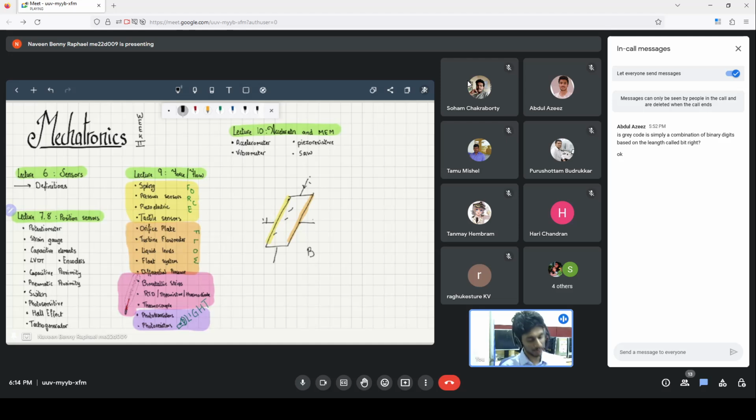If not, let's continue to force, flow, temperature, and light sensors. For force sensors, a spring is naturally a very intuitive thing to use, because instead of measuring force, using a spring we can measure length instead, and we already found several ways to measure length.